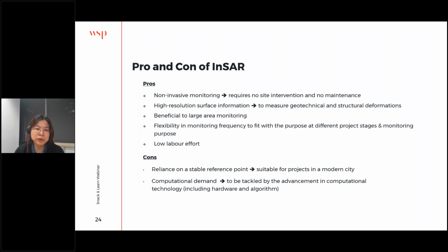But again, I would advise, based on our experience of the last 2 years, that field measurement comparison and calibration is very important, because back analyzing or curve fitting may say that the accuracy could be 2 to 3 millimeters, but based on experience, for predictions and for the trends, it has to be compared with manual field measurements.